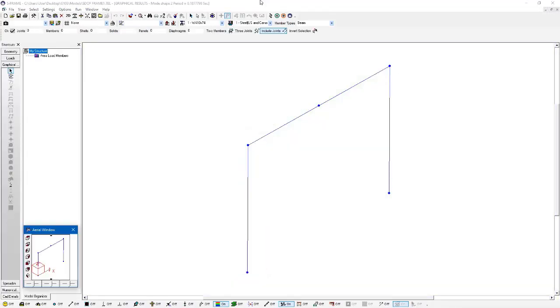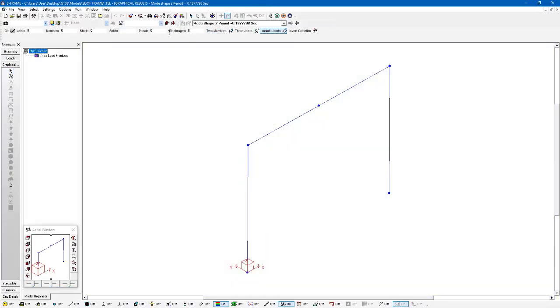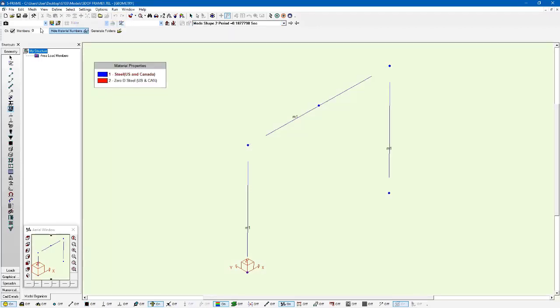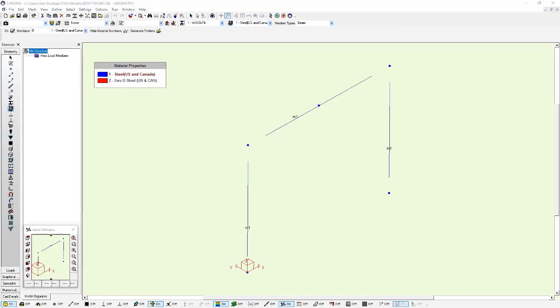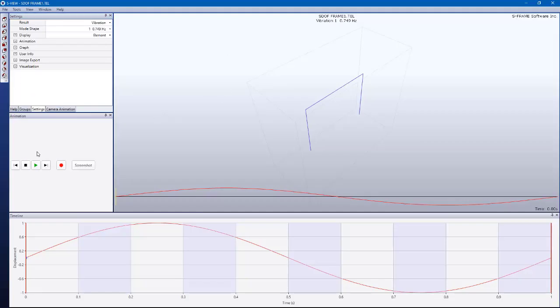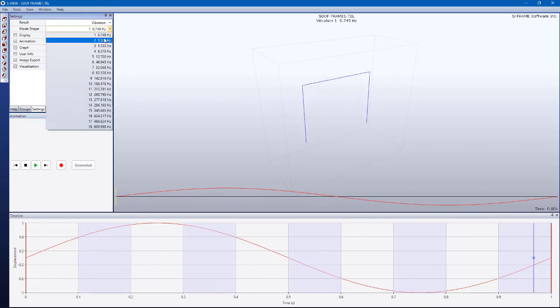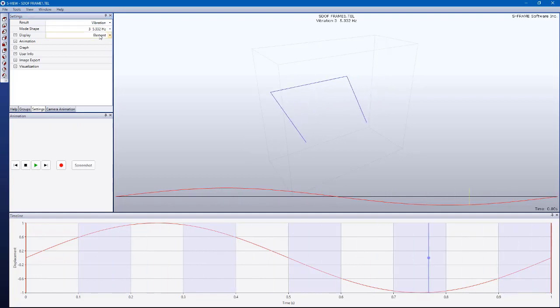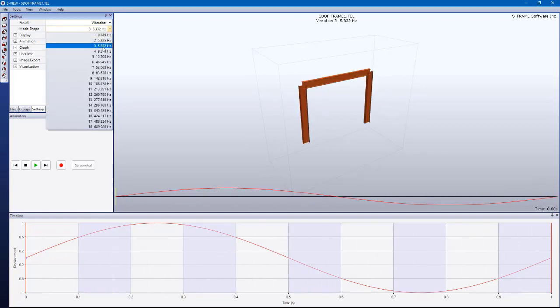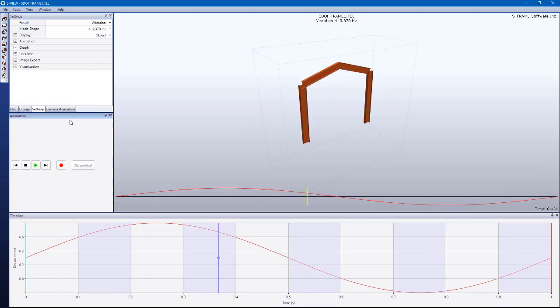We get a clean solution. And now if I look through the results here, I can see the number of different mode shapes and their associated periods. And we can actually view this in S-view. Maybe S-view is a better way to understand these mode shapes. And I'll be able to see what's going on. So in S-view here, I can look at each mode and see the direction that it's occurring in or oscillating in. I personally like S-view because we can also render the object view. So I can just get an idea for what each one of these looks like.